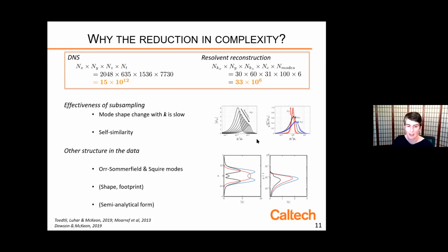That is to say, for the turbulent mean U, we know how that scales with distance from the wall and with Reynolds number. There are distinct scaling regions, and that's also impressed onto these mode shapes. So I can collapse these modes on the left to the ones on the right using the scalings that come from the mean profile. So that all helps.